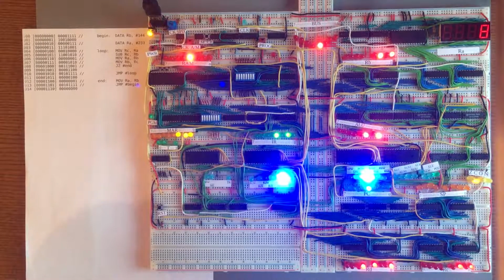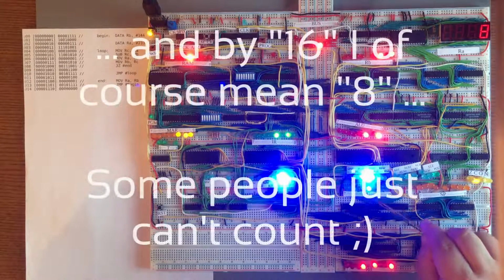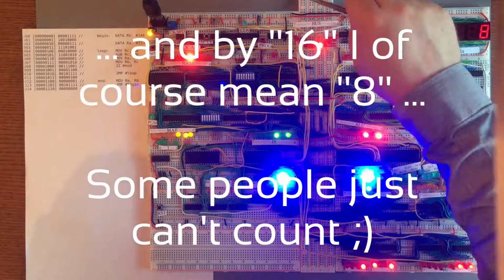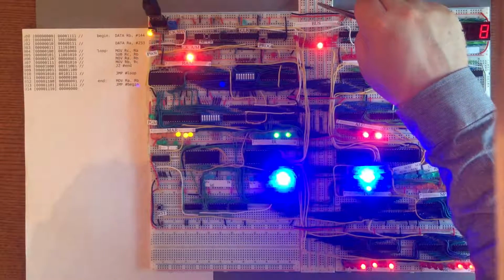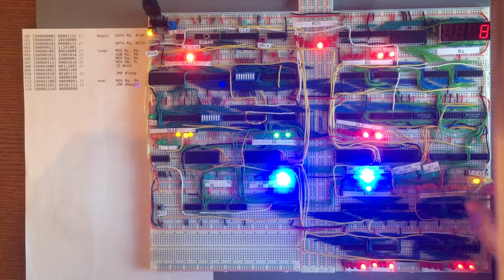So in this case, for example, we see that the program counter is enabling its value onto the bus. So this is the program counter, and at the moment it contains a value of 16. And so that 16 is asserted onto the bus, onto all 8 bits. And so that means that this line really is at 0, so is this one, so is this one, so is this one. This one is at 5 volts, this one is at 0, this one is at 0, and this one is at 0.